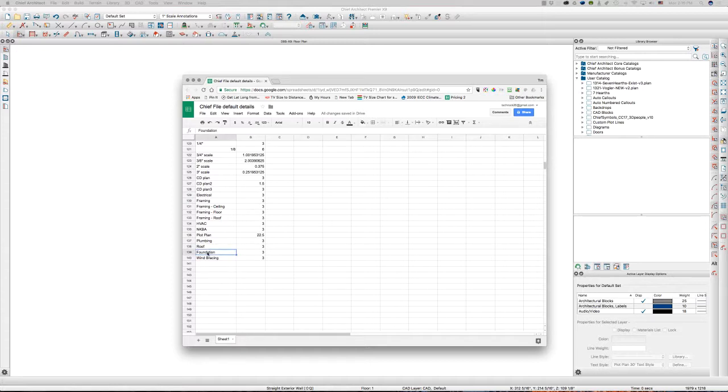Foundation plan. Now I think I mentioned this last time. I use the foundation plan separately from a level 0 architectural plan, because sometimes I want to show the architectural set being the living space, but I need to show the foundation plan to be clear, with the slab, with the footings, with step footings, with the foundation.